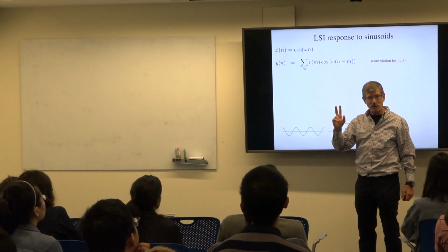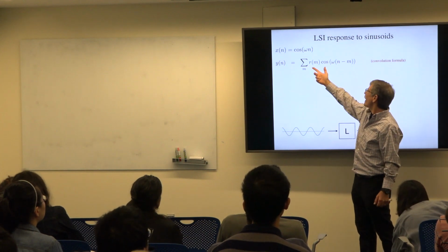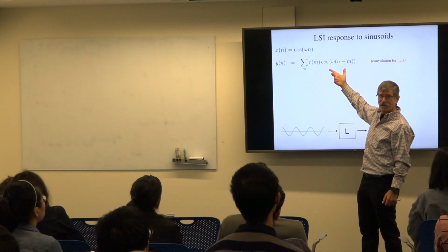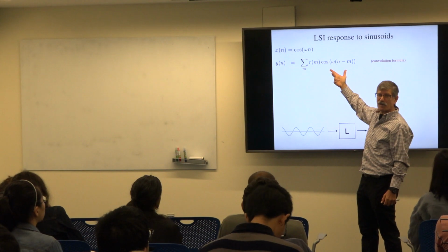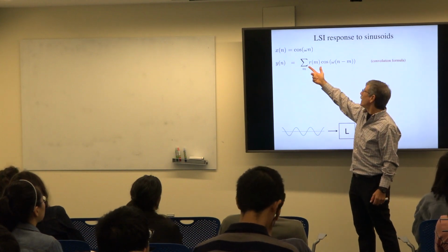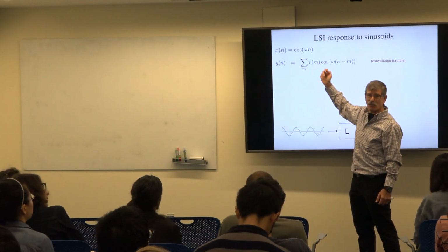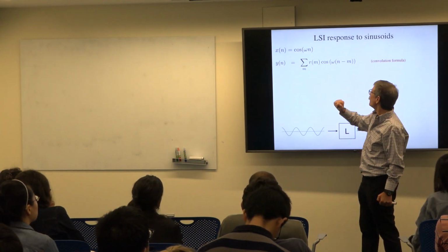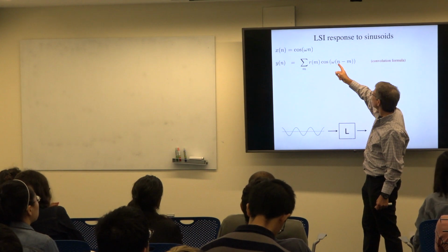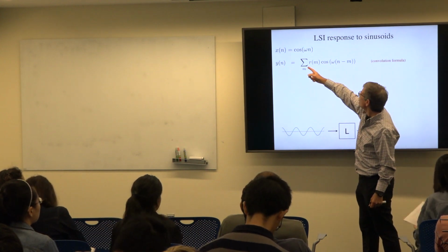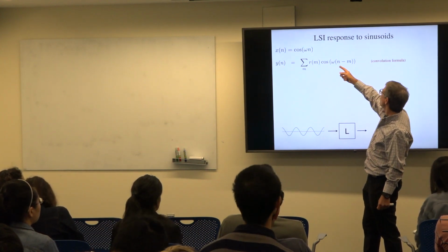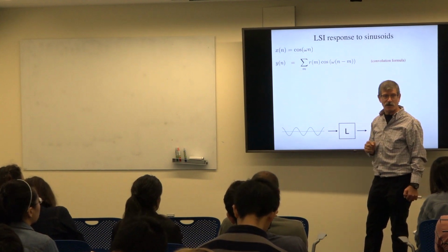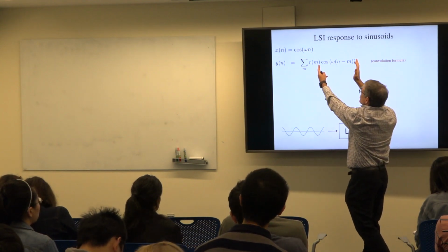Now there were two convolution formulas. There was one where R runs backwards and the input runs forwards. And there was an equivalent one where the input runs backwards and the impulse response runs forwards. So this is the second one of those. Okay, so everybody recognize the formula. N is the length of your vector, and as we run forward through the impulse response, we run backwards through the input signal. We're going to put this into our system.